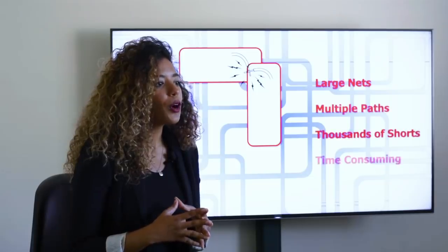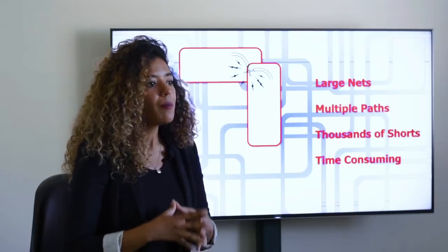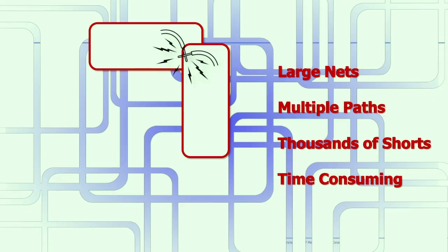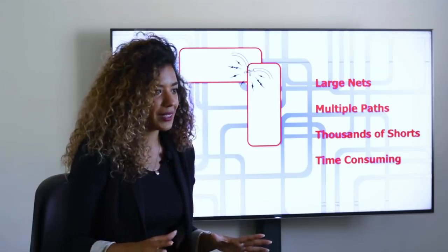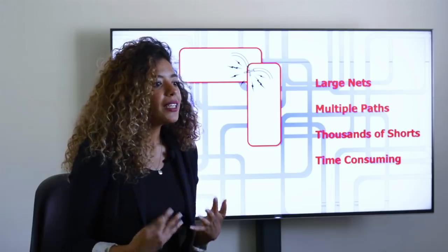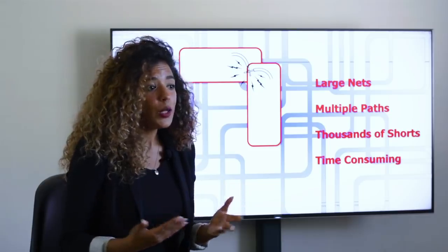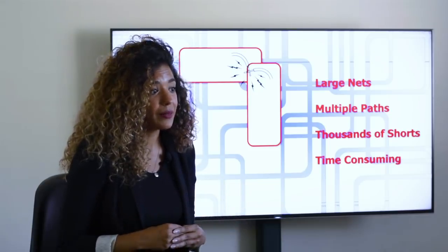The comment from the design teams is that they spend the majority of their LVS debug time on addressing the shorted nets. Now, imagine a dirty design with thousands of shorted nets. This will occur on both long and shorted nets. Many times there will be a power ground short. If you've ever opened up a power and ground short in the debugger and highlighted the path, the entire circuit lights up. To fix shorts, each shorted path needs to be analyzed and fixed because eventually you cannot risk a short circuit in your design.